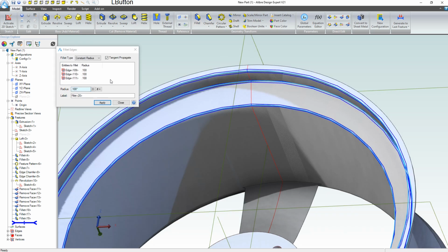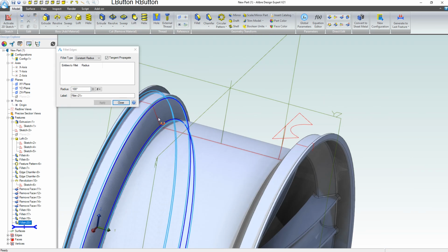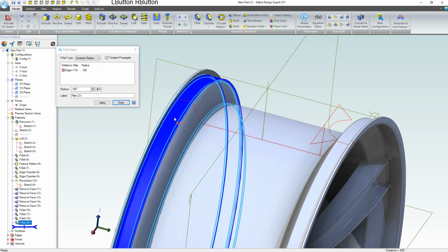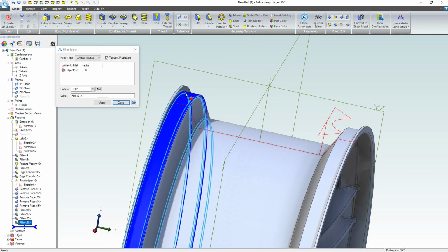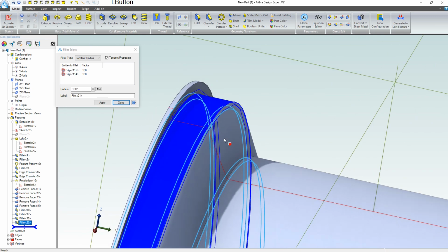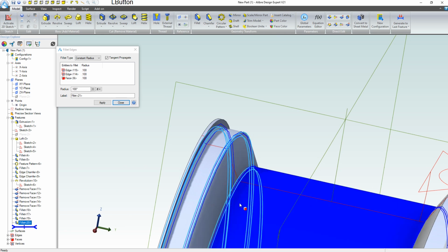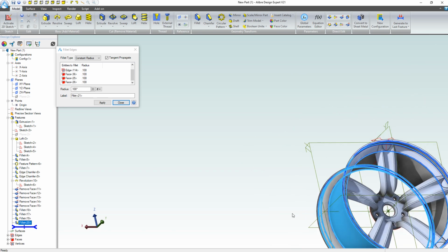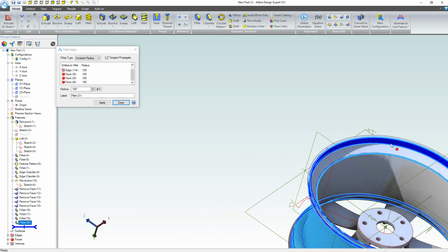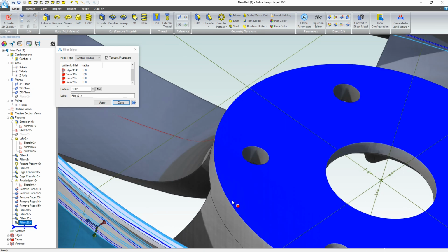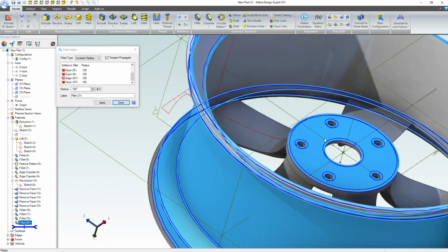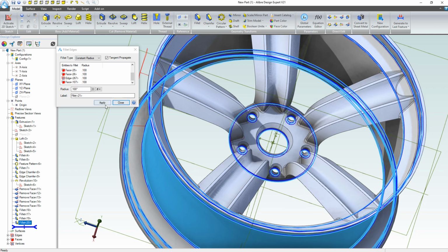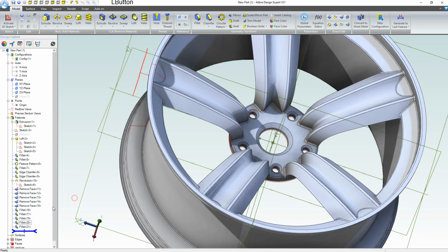Now I should be a little bit more considerate in my fillets and have a constant thickness for these. That would mean that this outer fillet would be the size of this inner fillet plus material thickness. I'm not being that careful right now. So do as I say, not as I do, I guess. Because this is just kind of a quick and dirty test to see what I can get done. And wow, this is really powerful. Hardly any fillet errors at all, and no error on that.